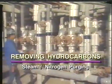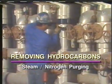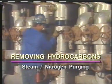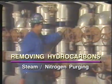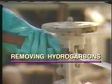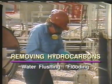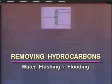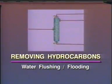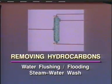One way to remove hydrocarbons from a tower is to purge the column with an inert gas like steam or nitrogen. Inert gases can strip or displace hydrocarbons off metal surfaces inside the tower and move these vapors out of the column. Water can also be used to clean out a tower. Some columns are flushed out with water and the liquid containing hydrocarbons is drained out the bottom. Other towers are completely flooded with water. The flooding operation floats hydrocarbons to the top of the column where they are removed. In some instances, a combination of water and steam is used to clean out the tower.